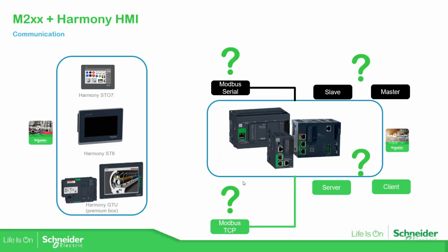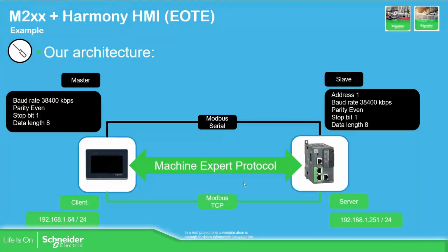In this controller we have the possibility to communicate with the HMI via Modbus serial or Modbus TCP. But in this example, what we're going to do is define these communication parameters, for Modbus serial and for Modbus TCP, on the PLC side and on the HMI side, in each software: the Operator Terminal Expert on the HMI and the Machine Expert on the PLC side.